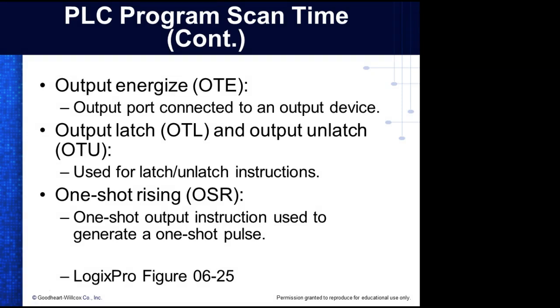These are output connections to an output device. Output latch: we have the ability, and we'll show this too, to latch an output on, and it will stay on until we unlatch it, which is a really neat instruction. That really simplifies what we can do.